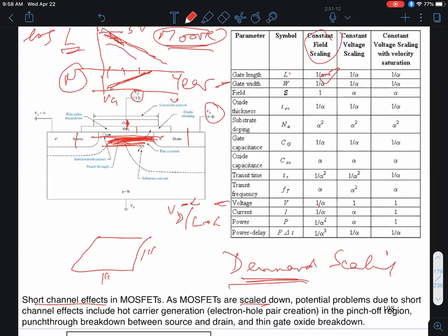As the channel length shrunk, the electric fields kept increasing until the problem got so bad that even circuit designers said, okay, we'll give up, and let the power supplies go down from 5 volts to 3.3 volts. It stayed at 3.3 volts for several generations, while the problem of increasing electric fields continued. Then it went down to 2.5 volts and so on.